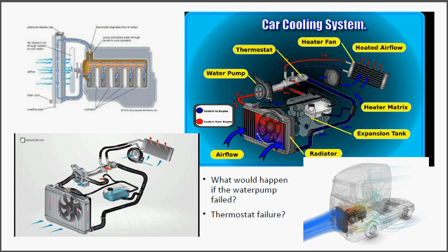You can change it within a very short time, but normally you don't have a thermostat at hand. I think in my driving career it's only happened once. Twice actually, it's happened twice. I had it on 2 cars, where I had a thermostat fail. Once it's broken, it's normally stuck closed. That's my experience. The temperature of the engine goes sky high, and you really need to change it.